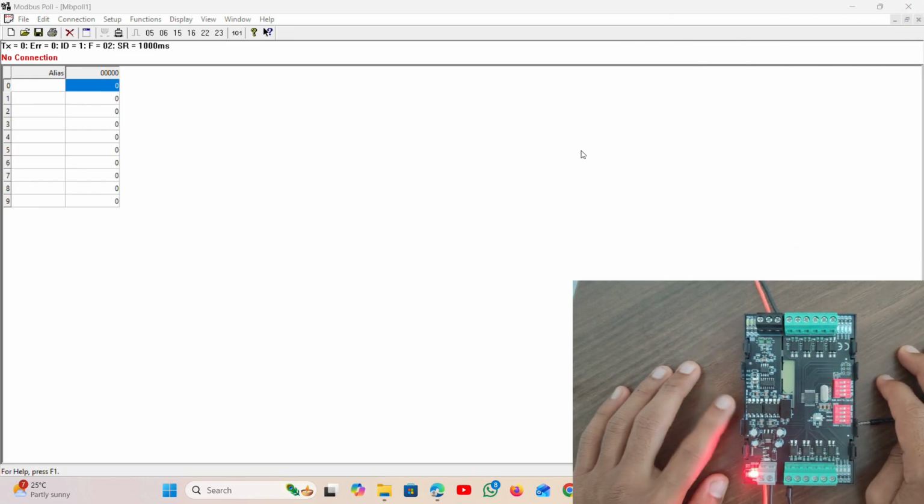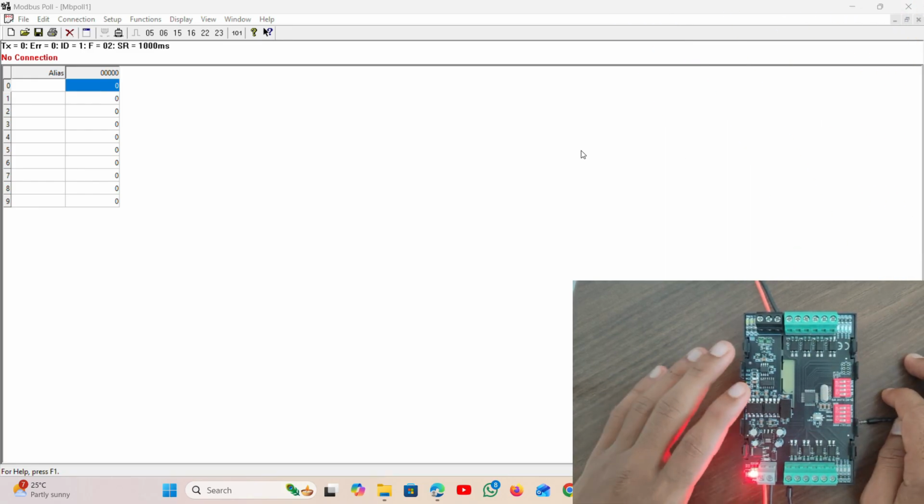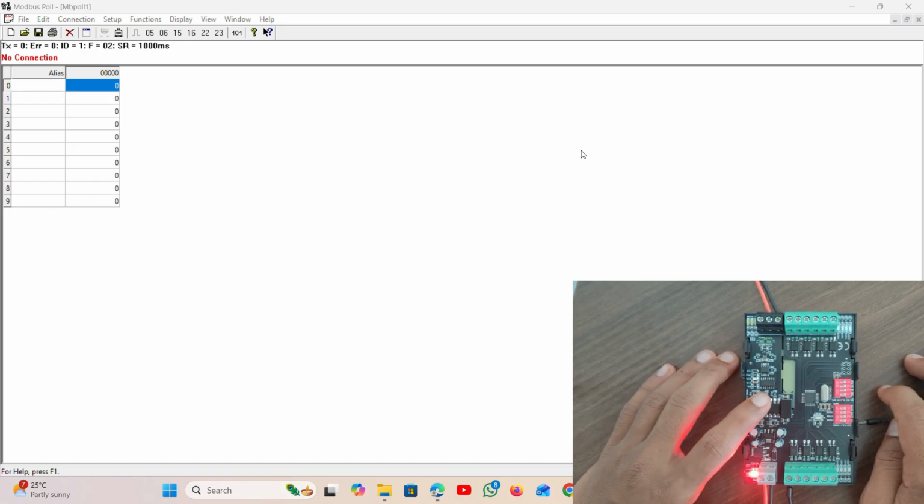This video is for the DI part. So for the DI we need a reference of 12 volts. So here I have connected the 12 volts with a male to male jumper.